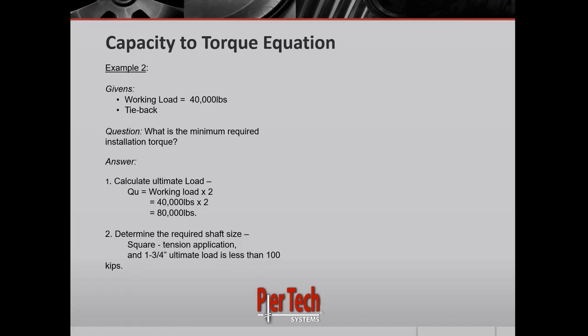So I would bump it up to the 1 3/4" shaft. If you chose 1.5", don't be upset with yourself. It's completely understandable why you would choose that, and you'll learn over time that you want to be cautious when choosing the pile and keeping it about 20% or so away from its maximum ultimate capacity.